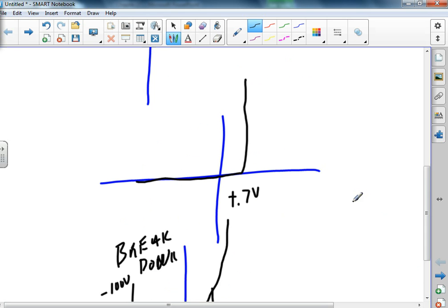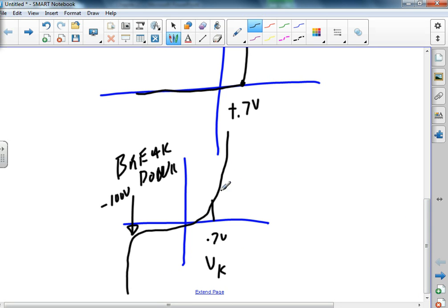A second approximation of the diode, well, I need some forward voltage to turn it on. And then a more scientific approach saying that, well, there's something that happens in the breakdown region, there's something that happens at the knee, and I'm passing current through it if I'm forward biased, and if I don't, I don't. And this amount of current is very small, microamps, and I'm on a milliamp scale going up that way when I'm volts on that side.